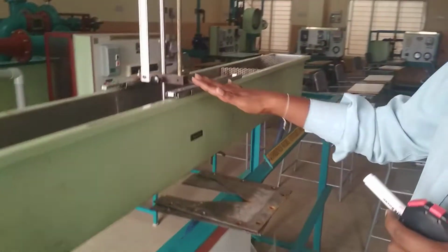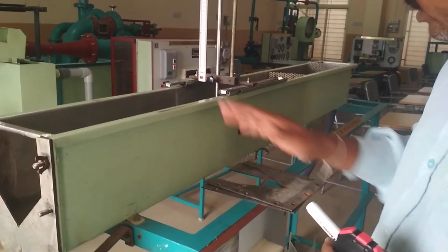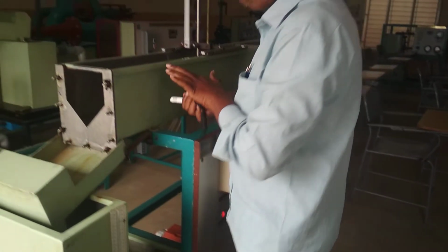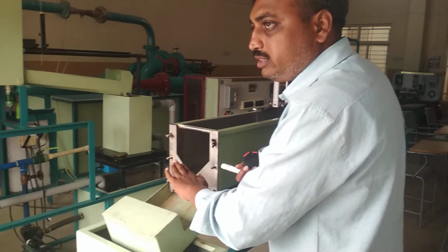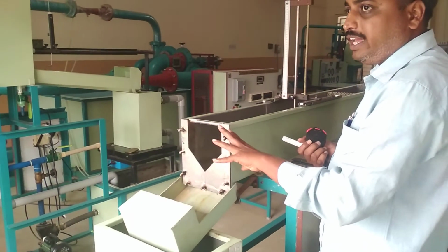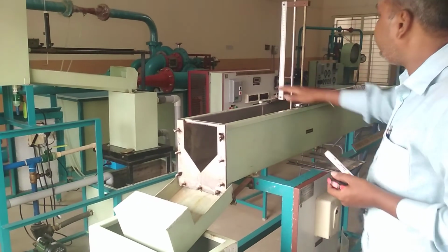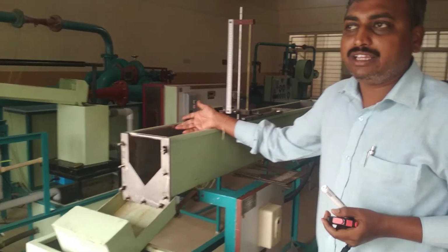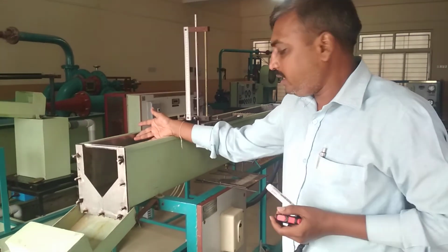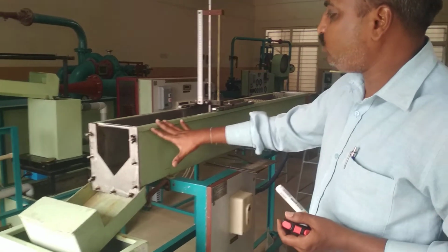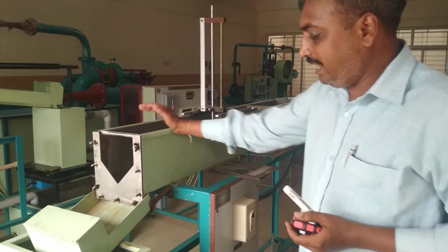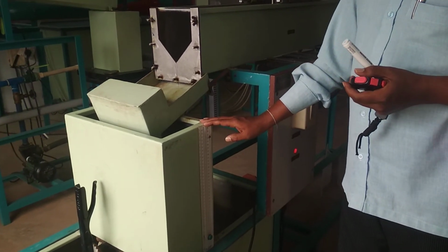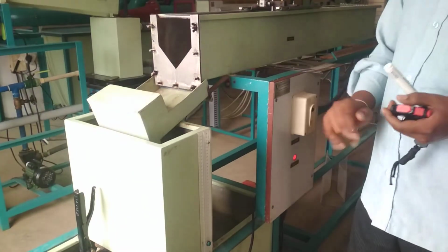Once the water is completely settled down, now you can switch on the button. So whatever the amount of free flow of water, it will take place. You need to wait for some time. Later, once again you set this pointer gauge for that level of water, and you take the reading, that is h2. Once h1 and h2 readings are taken, then you need to find out the time for collection of water in the collecting tank.